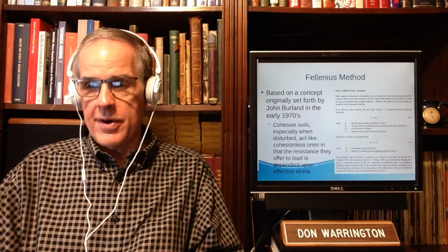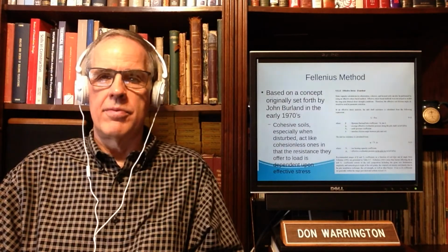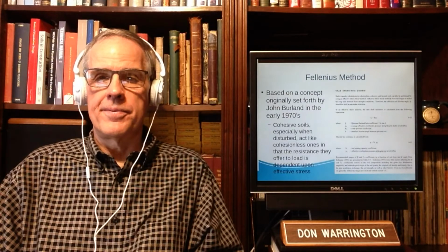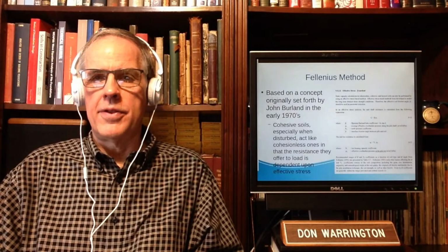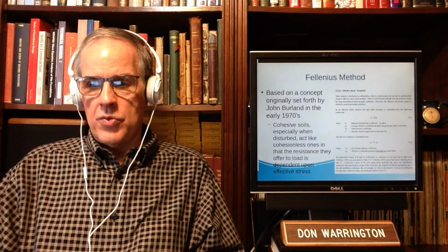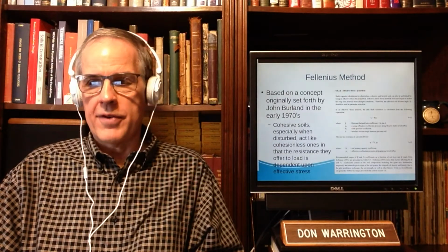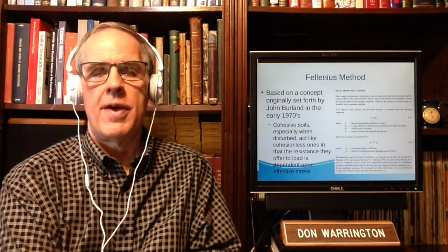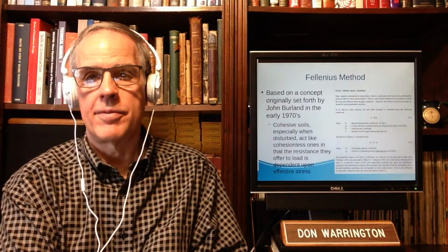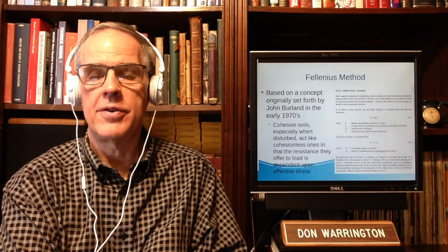And it's based upon a concept which I think is subject to revision, and I'm going to explain why. Particularly Tomlinson's method, I think, needs a good overhaul. There are 2 methods that we use, particularly for shaft resistance, which are called alpha methods and beta methods. Alpha methods, like Tomlinson's, which your book describes in detail, we use with clays.